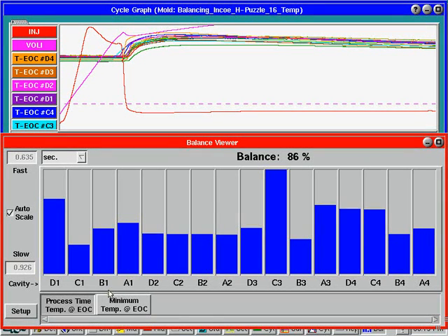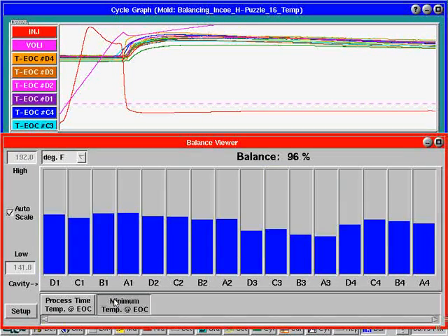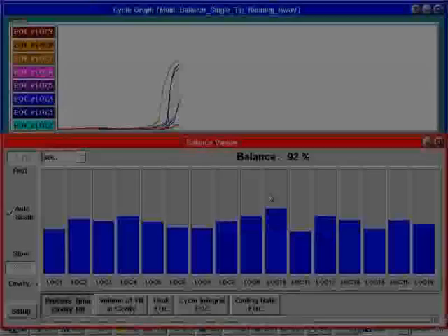While waiting for the finishing touches, let's look at the other useful plastics variable that you get from temperature sensors, cooling temperature. The minimum is the temperature of the steel just before the plastic arrives. Clicking the minimum button, you see reasonably good balance between the cavity temperatures and thus the cooling. There is a pattern, though, showing that some are slightly colder than others.